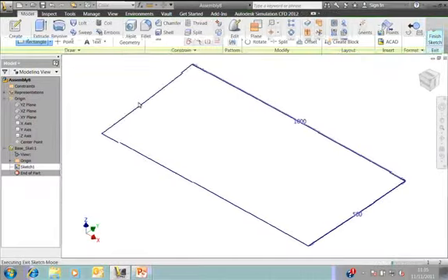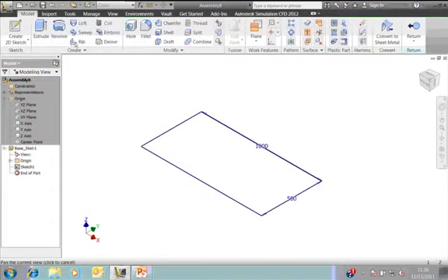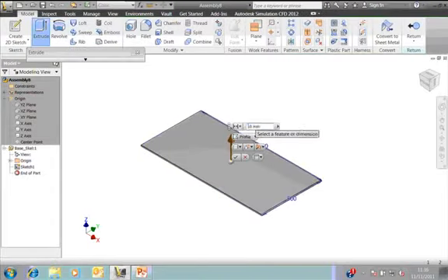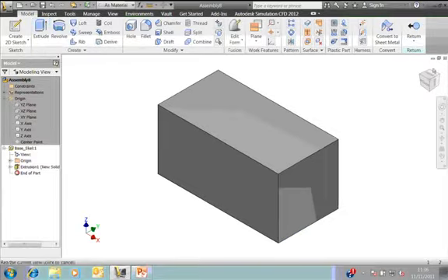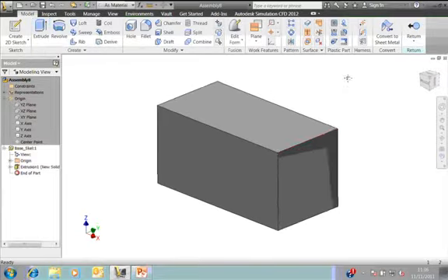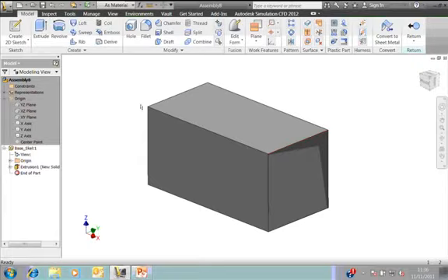So model your skeleton as a solid model instead. It's a lot quicker than working with 3D sketches, and we still have the ability of selecting the edges on this model to place our steel sections later on. If you've got any other braces or struts, then you just add these as sketches on the faces.